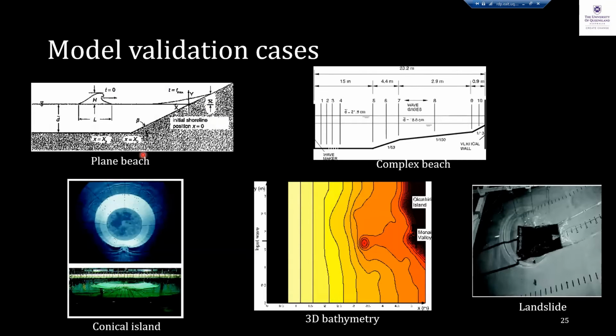Apart from the experiments which I'll be talking about, I also did some numerical modeling to see if the numerical models that we currently have in tsunami warning centers can issue a correct tsunami warning if there is a tsunami wave going up a river. Usually these models are validated against benchmark cases. So one is a simple case where the wave is just going up a plain beach. The second case is it's going up a complex beach. And then we have some 3D scenarios where we look at the wave transformations. But there's no data set against which the model can be validated for tsunami in rivers.